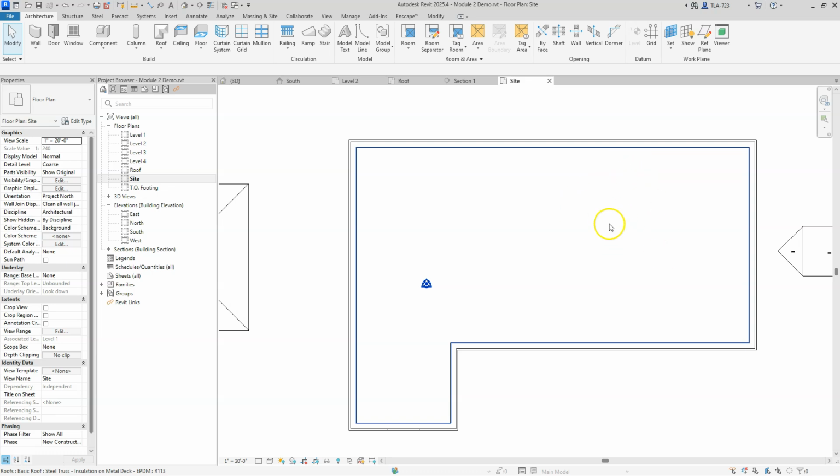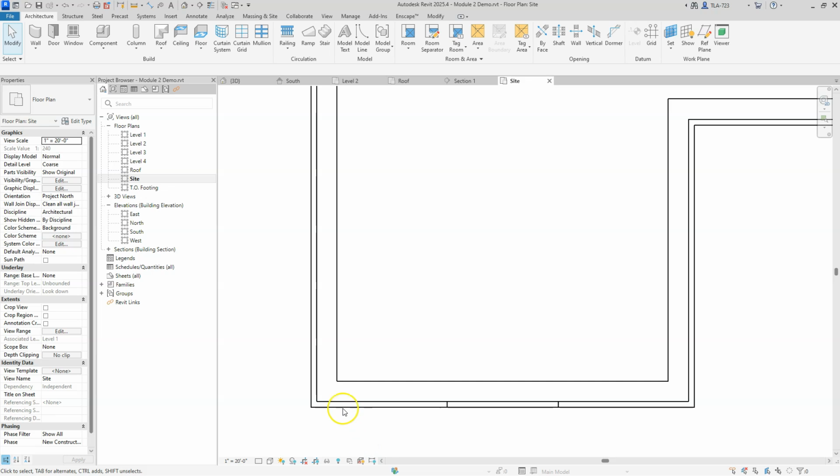Okay, so what we need to do is come up with a strategy on how we're going to slope that roof. Now, you see a lot of different roof styles and a lot of different strategies employed, but as I look at an L-shaped roof like this, I think it makes sense to come up with at least 3 drains. Maybe one for this half of the big building, one for this half, and then one for this little area down here possibly. But again, there's a lot of different ways that we could break that up.